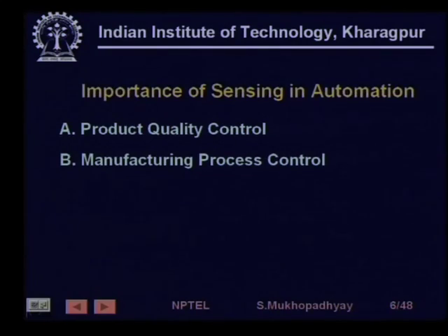In process control, if you have a rolling mill and you want to control the roll thickness, then you have feedback, or most all process control is actually closed loop feedback control, about which we are going to learn in the future lessons. So, for that a critical element is the feedback element. The variable which is being controlled, it may be thickness, it may be temperature, whatever, has to be continuously fed back using a sensor in the loop of the control system, and the performance of the control system is actually critical to that of this sensor. So, sensing is of primary importance in control.